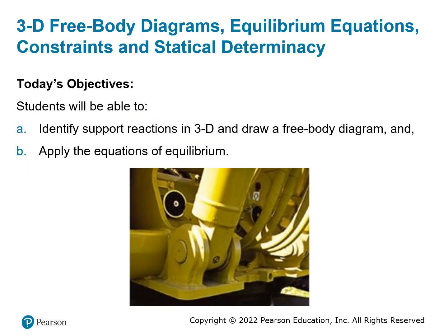So when you have a three-dimensional problem, how do you solve it? The objective for this video is to show you how to identify the support reactions for a three-dimensional object, and how to draw a free body diagram of that. Then we'll use the equations of equilibrium to solve the problem. The equations of equilibrium will be expanded to 6 equations instead of just 3, so you're going to spend more time solving a three-dimensional problem.